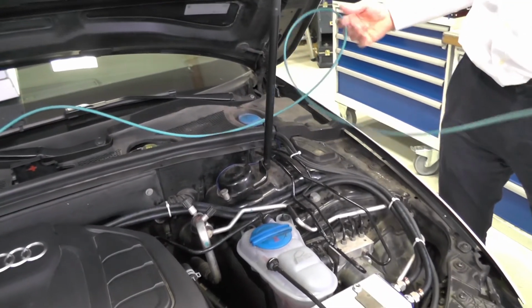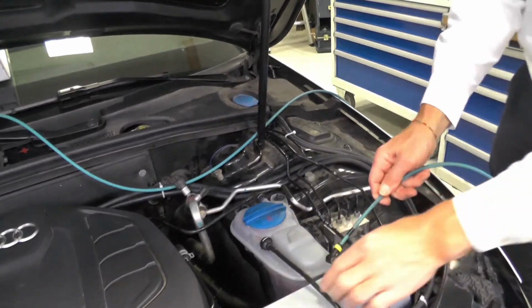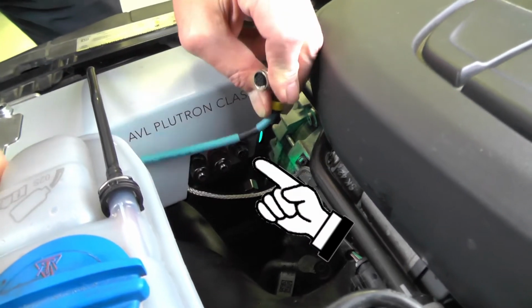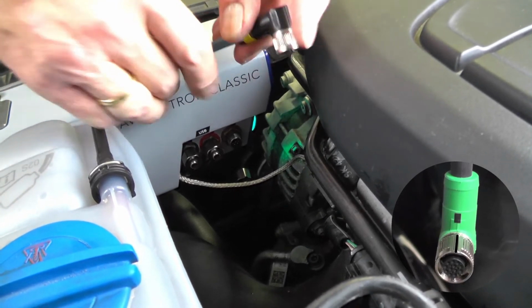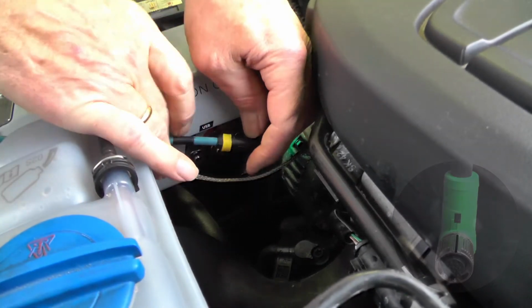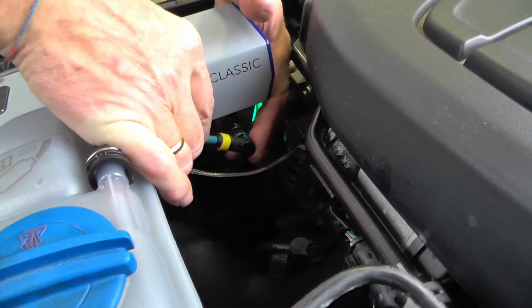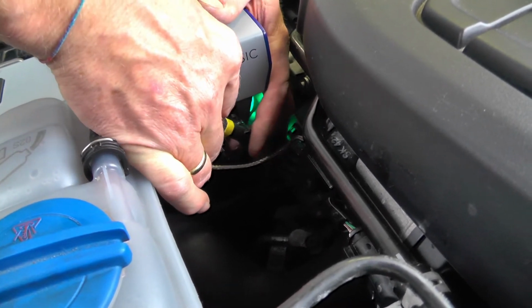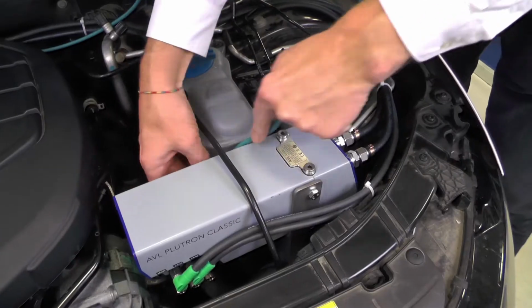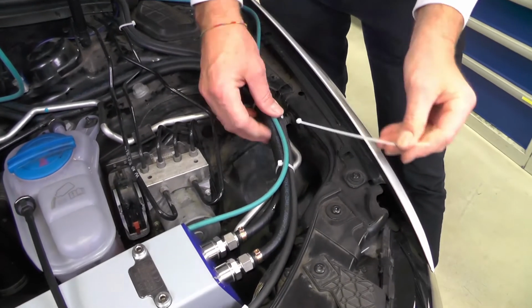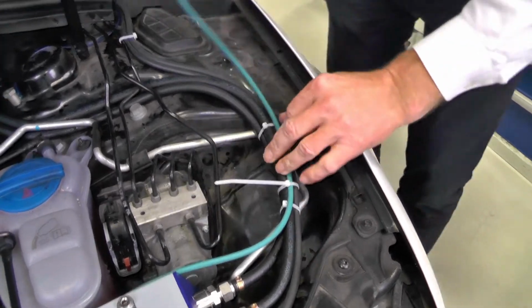The connector is plugged to the socket marked ETH for Ethernet. Remember, the connector locking ring mark needs to be aligned with the bar marking on the connector. Then it can be easily plugged and locked even in poorly accessible positions. We complete the installation by fixing the cables with zip ties.